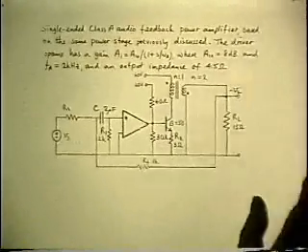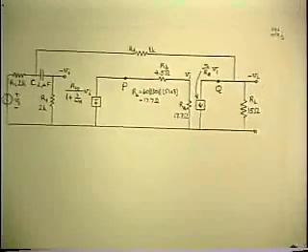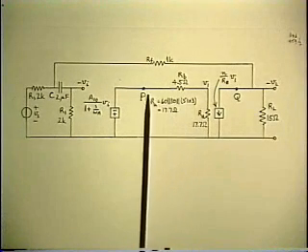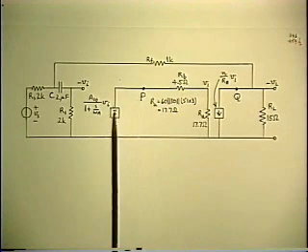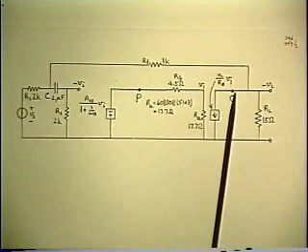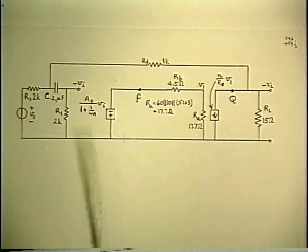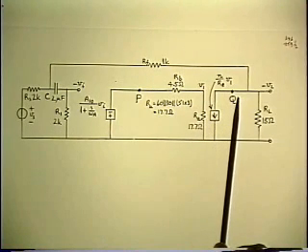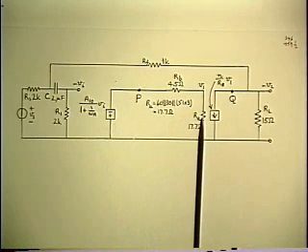Once again, if we go back to this little power amplifier model as an example, this was the first version of the equivalent circuit that we came up with. And we looked at the relative merits of injecting a voltage at point P, where it's in series with an ideal voltage source, which was acceptable, versus injecting at a point Q, where it's an ideal current source, and we did current injection. And I said more or less arbitrarily, let's do current injection just to illustrate that method, which allows us to get rid of this internal loop and simplify the problem.